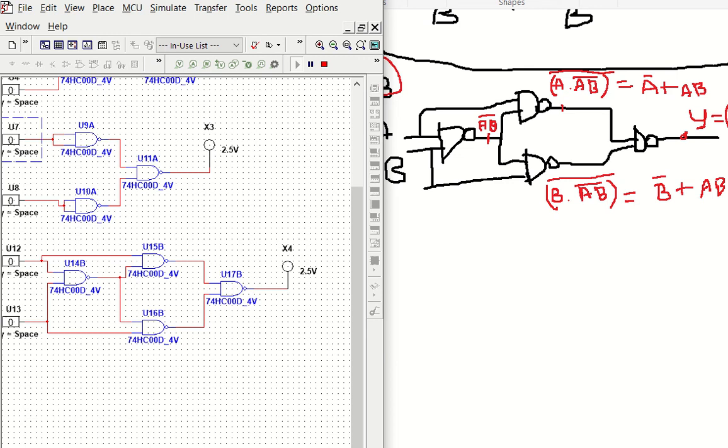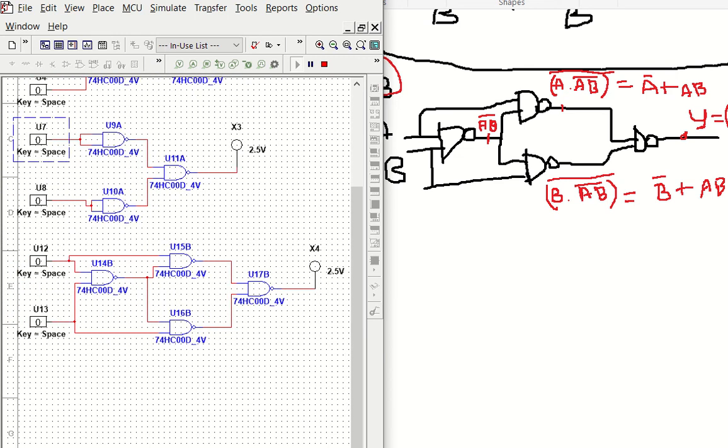So now we are going to check for XOR operation. If we remember the truth table of XOR from the previous logic gates video, for any unequal combination, whether it's 1 0 or 0 1 combination of inputs, the output is supposed to be high. So let's take 0 1 combination as well. You can already see that it is high, but for 1 1 combination it is low. So this was all about XOR gate operation.